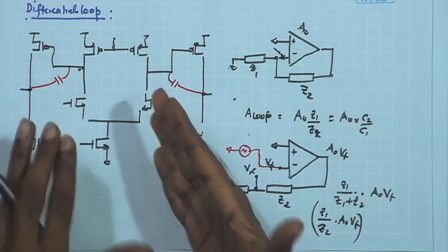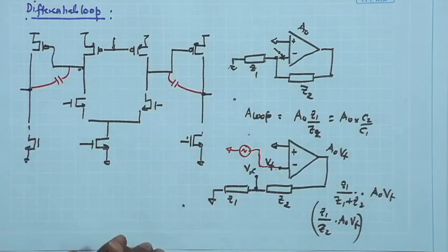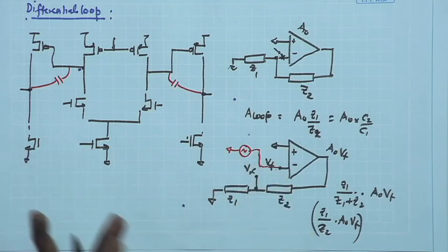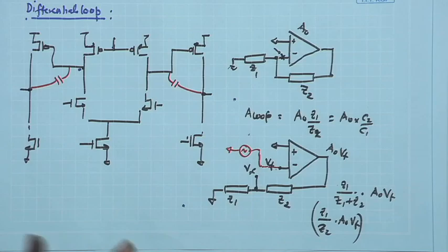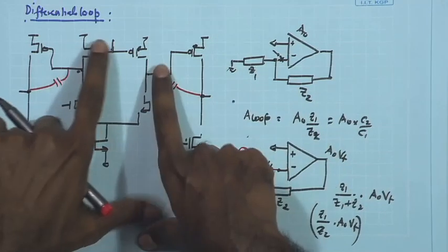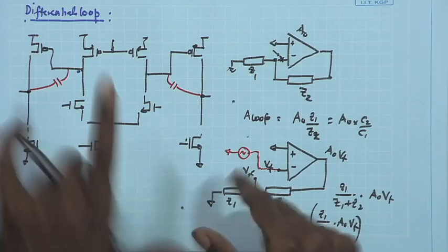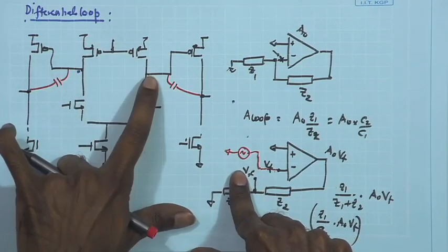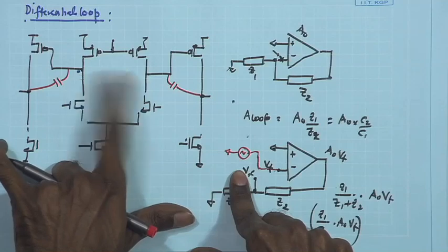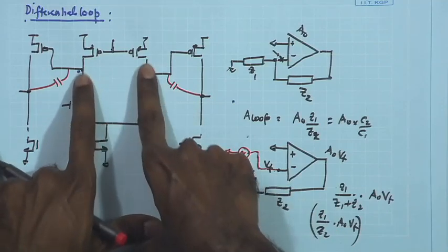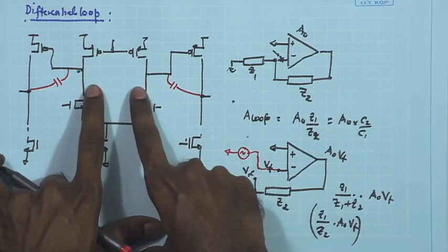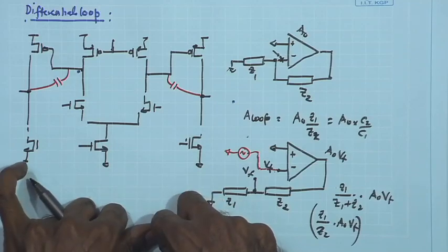As a result, for the common mode feedback case also, the magnitude of the loop gain was similar, not exactly the same, but similar. Now, why not exactly the same? You can recall that for calculating the common mode loop gain, you have to see the gain from this point to the output over here, the common mode output, and there rather than RO by 2 you get RO, because the impedance looking down into the drain of the MOSFET was pretty large.